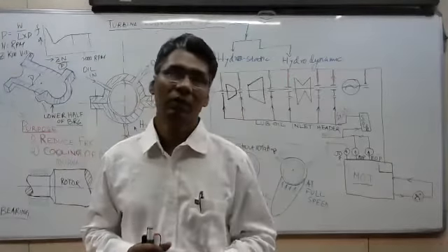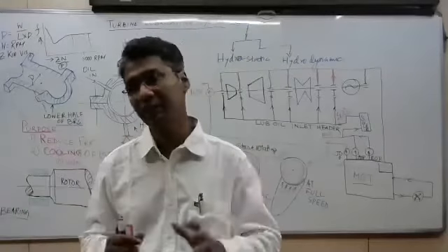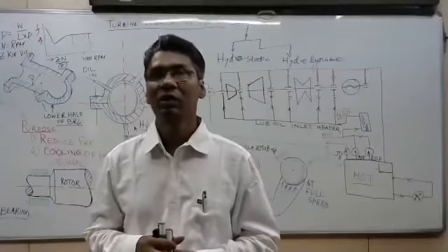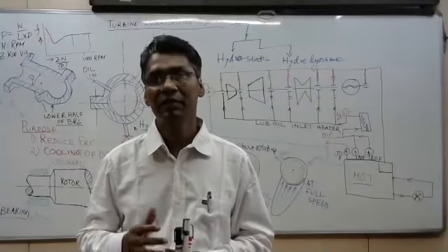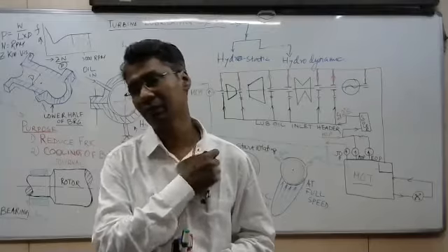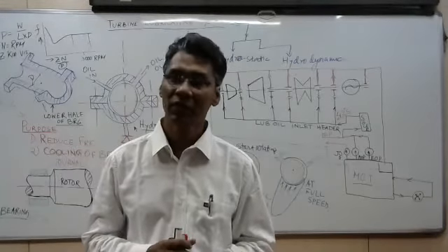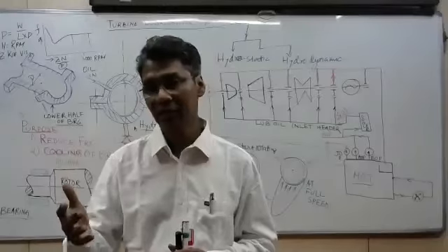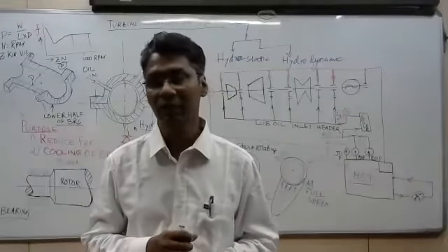However, the oil should be flown like this. So the cooling effect is like that. The bearing temperature should not go more than 70-80 degrees centigrade. So we have a tripping or shutting down of the power plant at higher bearing temperature. That is a protection that is there. So we have to have a protection at higher temperature. Otherwise, the bearing will fail and it will be a disastrous situation in the power plant.